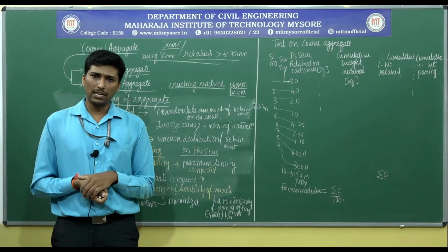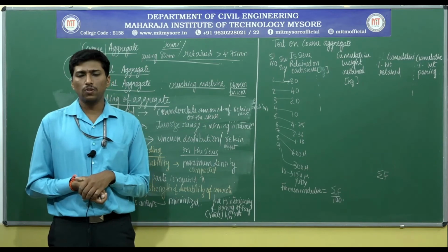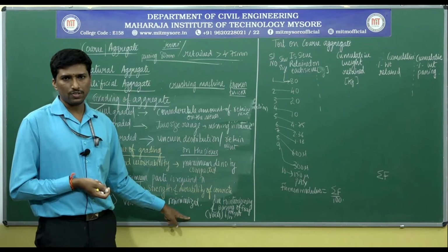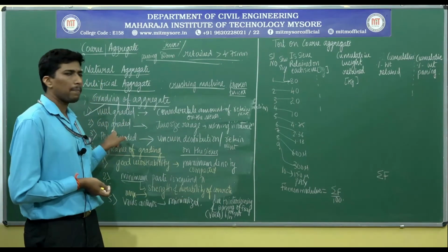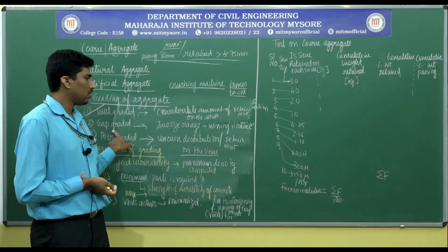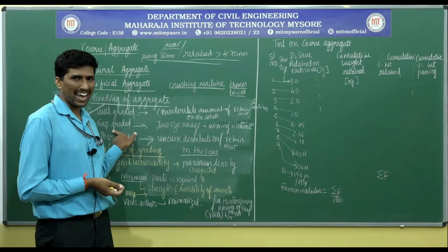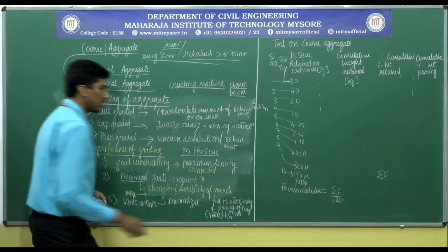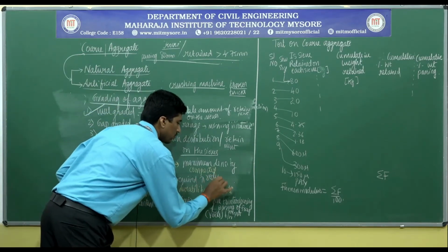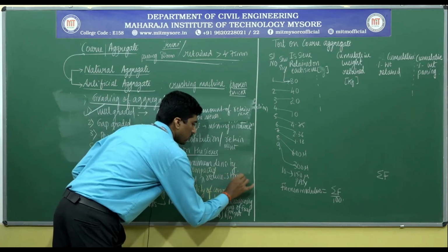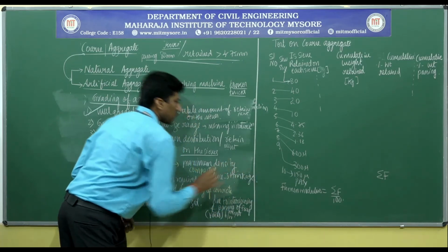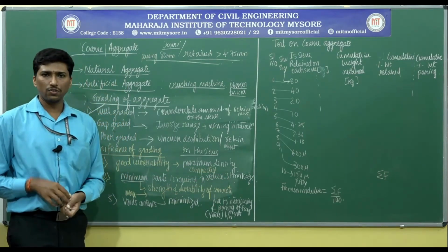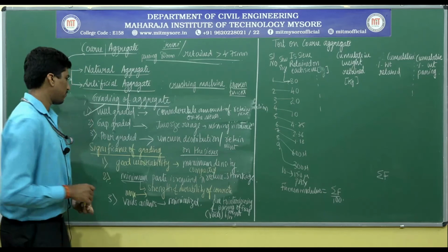The quality of the materials matters much. If the quality is good graded, then you can achieve all these things. If the quality is gap graded, no, not a way. Slightly you have some crackings and shrinkages. Major thing, it should reduce the shrinkage. These things you're going to study in concrete technology in the 4th semester.